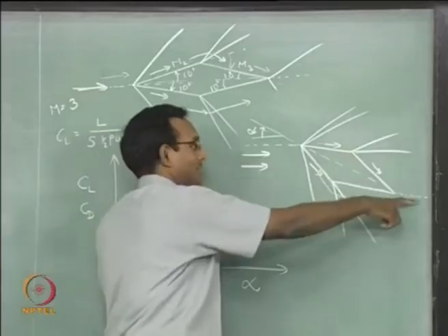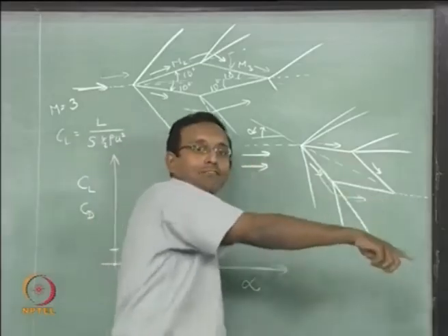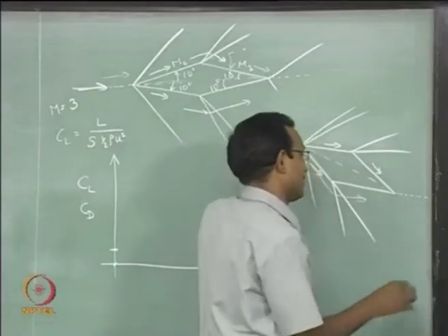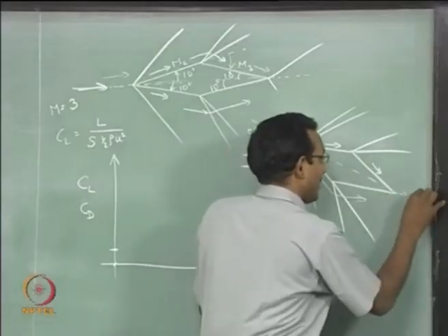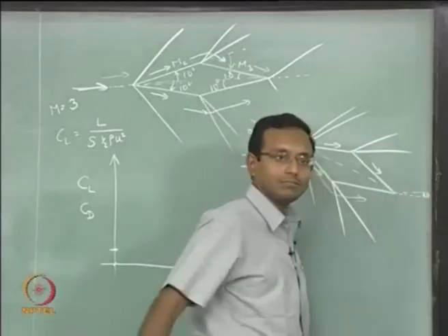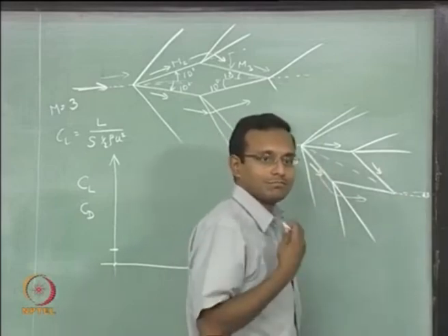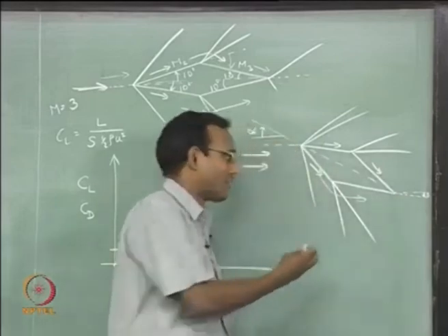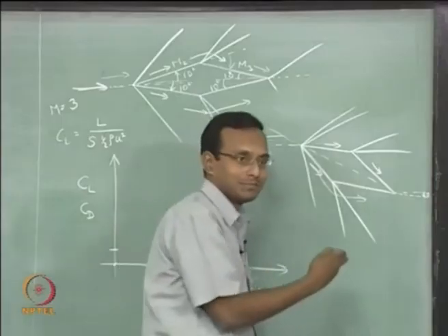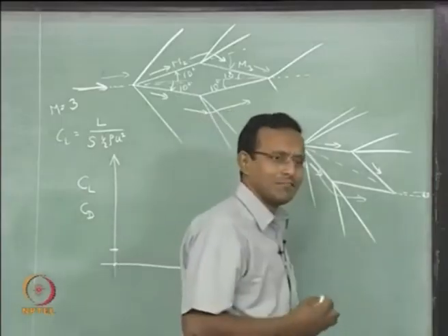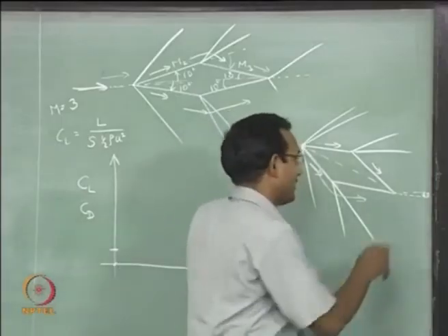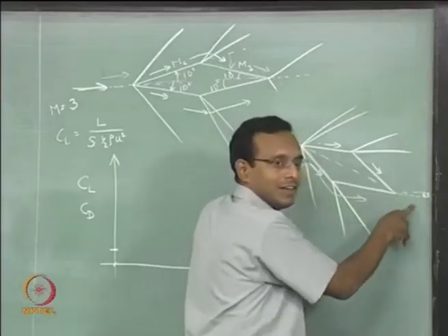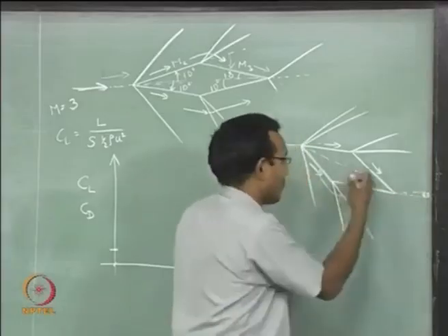It will go almost like the flow direction when it leaves the airfoil. Okay, almost. We will still have that small delta downward, just for completeness sake. I can call it 0 also, that will force the problem. We do not want to call it 0, let us say we find the angle, so that I will match the pressure and match this delta value for both sides.